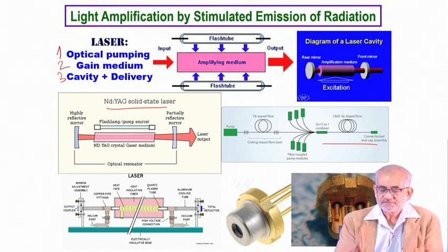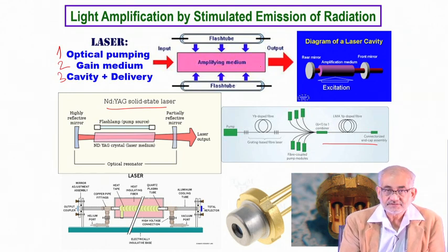Anyway, so these are various possibilities. Since I mentioned the fiber laser being one of the most widely used ones these days, that happens because it's very convenient. The active medium and the delivery medium are the same. So essentially long optical fibers, and some of them come with certain pumping devices, diodes which will actually pump energy into them, and so all of them will create a bundle, and that's where they get combined.